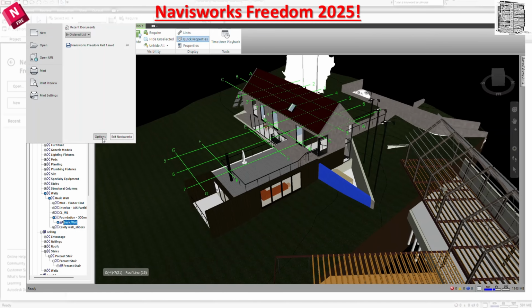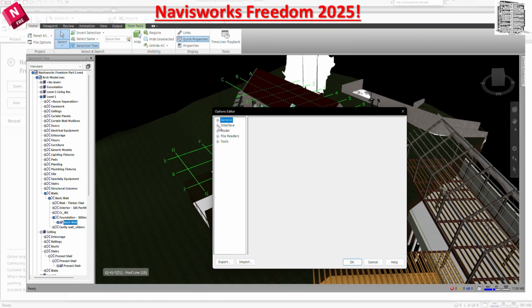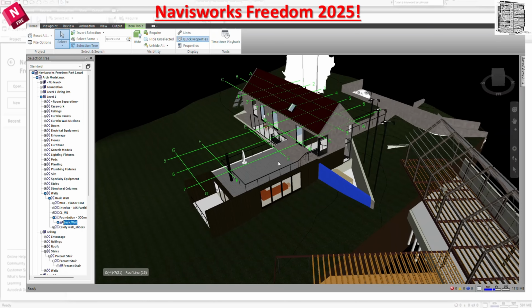And also, I know we reviewed in our previous videos, if you want to go to quick properties over here, definition, this is where you can add. So you can say, okay, I want name, type. If you want to add another one, let's do material. And then when I hit okay, if I go on it right now, it adds the material to the description.